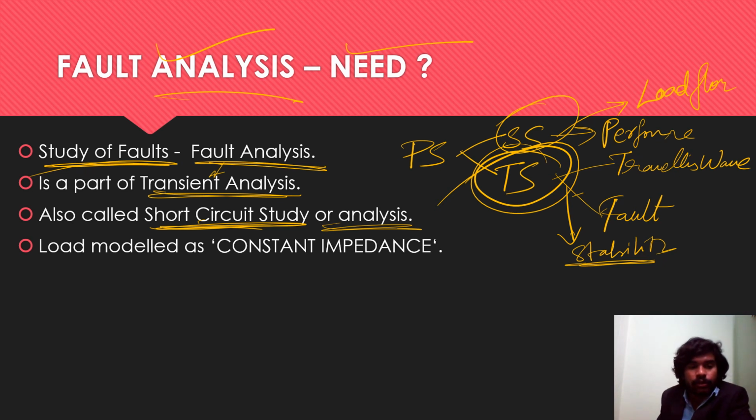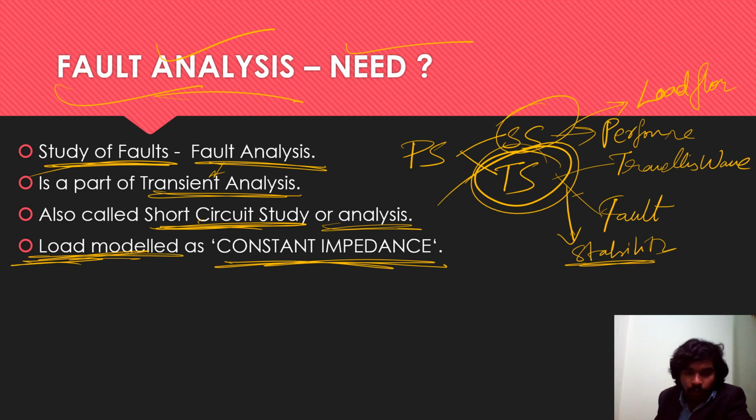Okay, and in order to carry out this short circuit analysis or fault analysis, the load usually will be modeled as a constant impedance. Now what is this load modeling, we will discuss in a later video, but for now it is a very important objective point for your exam, that load will be modeled in the form of a constant impedance. I will make a separate video regarding load modeling.